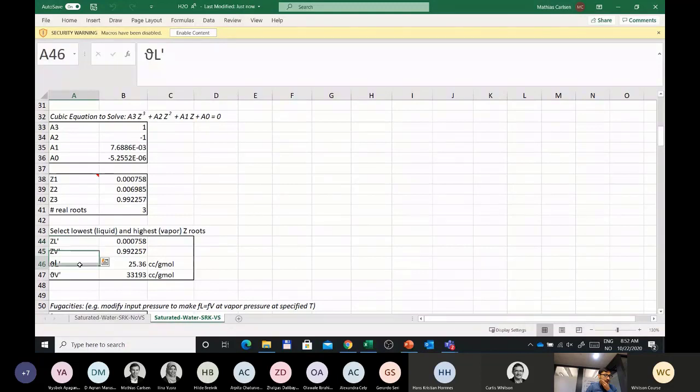So we have seen the correction applied on a molar volume basis, so that's why we calculate the molar volume first from the Z factor, and that's just simply PV equals nZRT. Knowing the Z factor, we can apply that equation. That will give us the molar volume of the liquid phase, and same using the vapor phase Z factor, we can get the molar volume of the vapor phase.